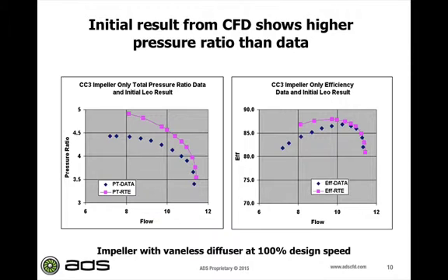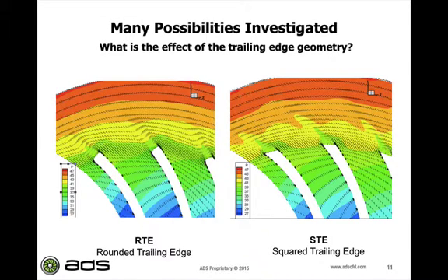Once through all of that, the next chart shows one of the most interesting and amazing outputs from my perspective. What you're seeing here is the Mach number distribution at 50% span around the trailing edge of the impeller and the splitter. On your left-hand side is the mesh we originally generated, because I myself have been working on axial compressors and axial turbines. Generally, those geometries have a rounded trailing edge. However, in experiments on centrifugal compressors, people generally cut off the trailing edge at a constant radius, which is no longer a rounded trailing edge. They are very sharp and are really at a constant radius.